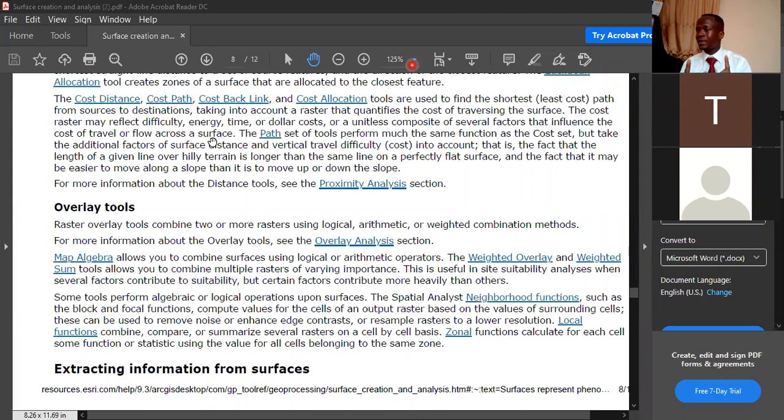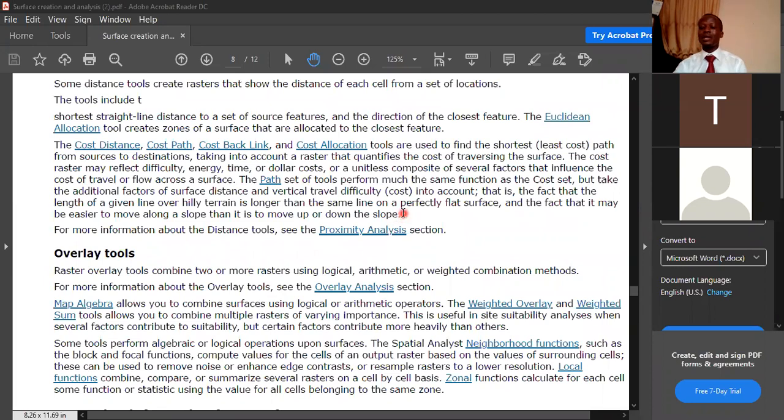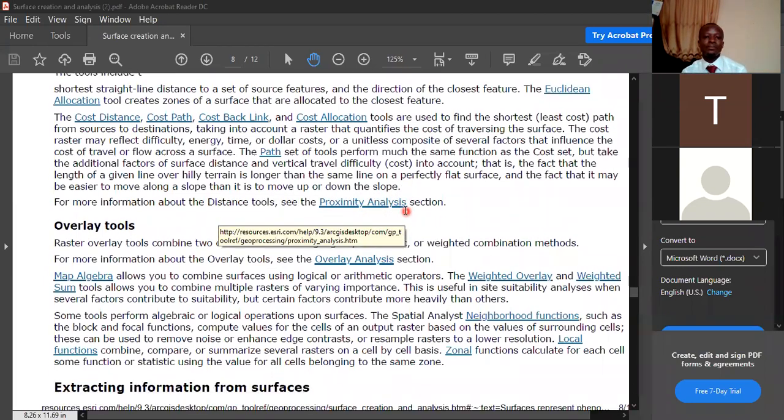It is very important to reclassify, so that we will have the same scale, and say that on a scale of 1 to 10 for the paved areas, this is the best place to put it. Meanwhile, in terms of slopes, this is the best area. Then we combine all of them, and we get a particular area which is delineated and can be used. Depending on the software, like I said, this material is based on GIS, so they'll be using certain functions that they already created, but the concept is the same: that we can overlay.